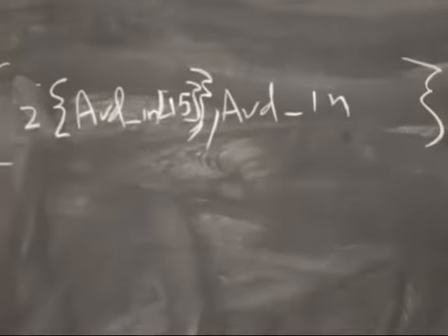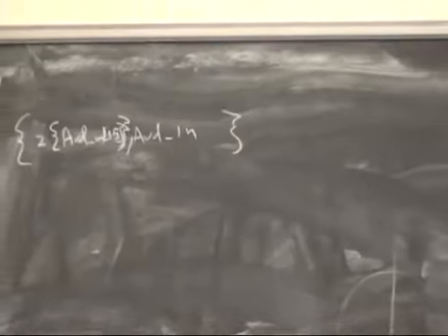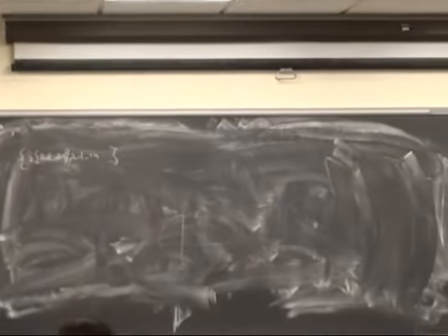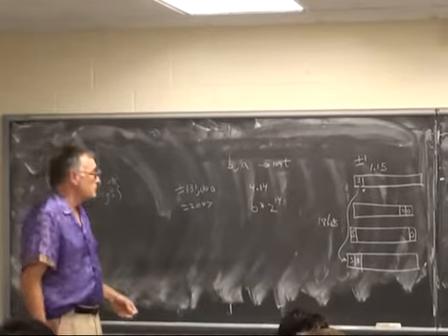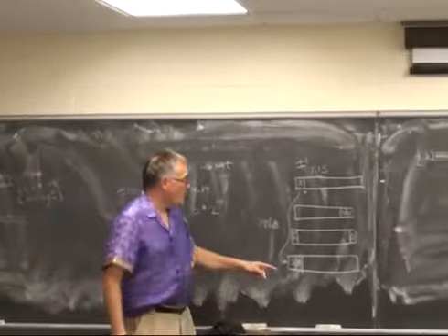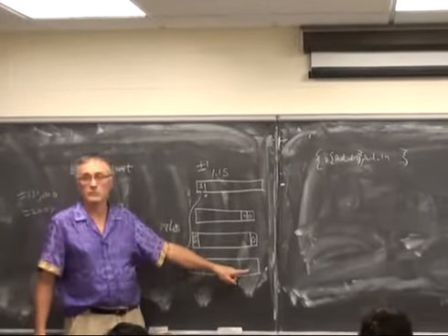You'll get a lot of crackling and go shh instead of sounding like a sine wave. You'll actually hear the second harmonic as a sine wave. And you'll hear a bunch of crackly sounds due to all of the discontinuities in the waveform. So you have to explicitly sign extend if you decide to right justify it.